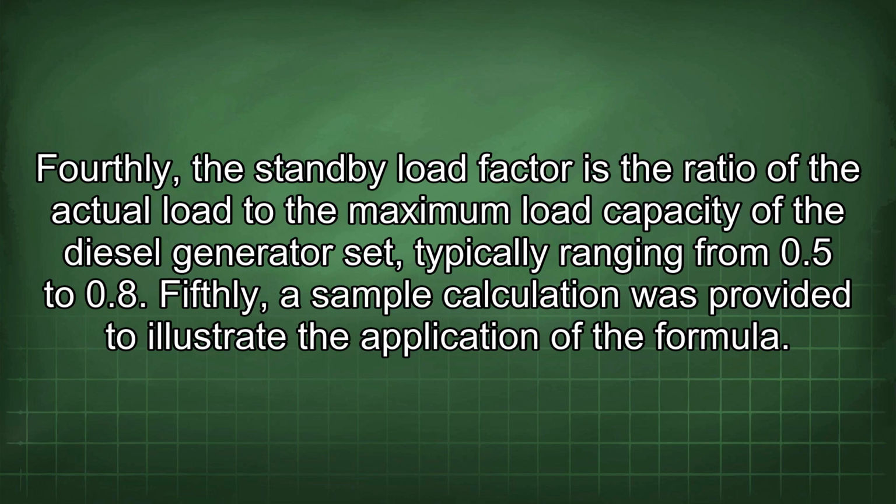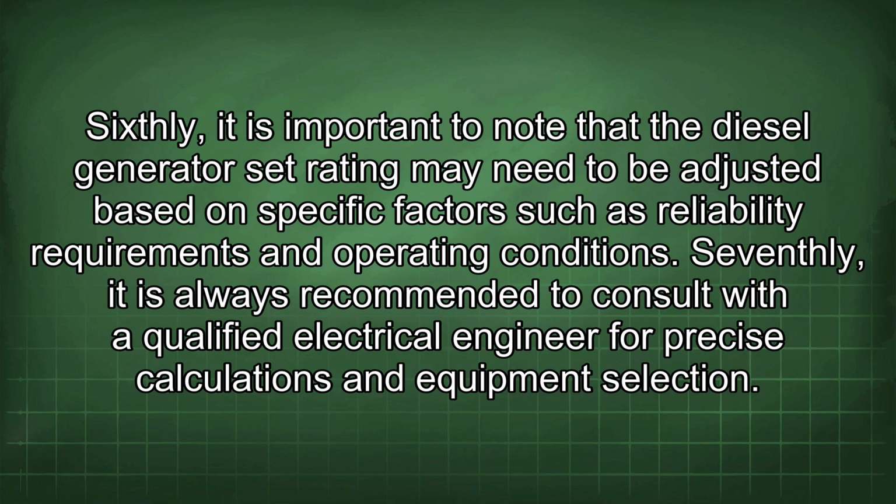Fourthly, the standby load factor is the ratio of the actual load to the maximum load capacity of the diesel generator set, typically ranging from 0.5 to 0.8. Fifthly, a sample calculation was provided to illustrate the application of the formula. Sixthly, it is important to note that the diesel generator set rating may need to be adjusted based on specific factors such as reliability requirements and operating conditions. Seventhly, it is always recommended to consult with a qualified electrical engineer for precise calculations and equipment selection.